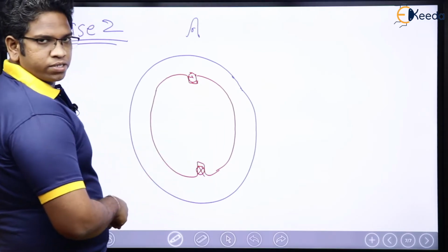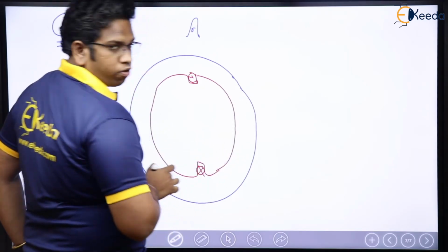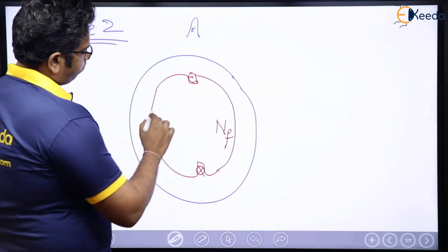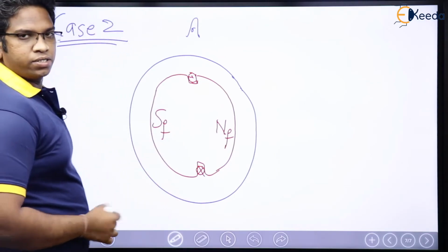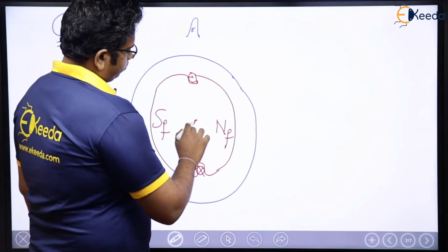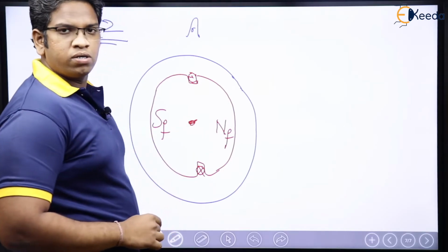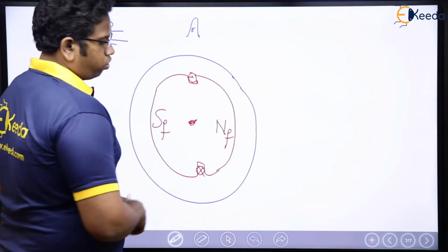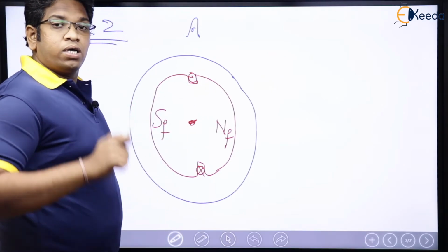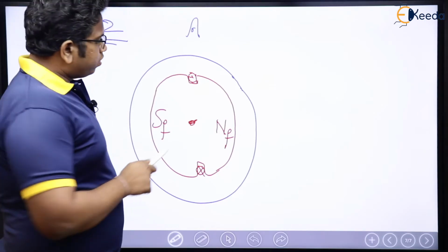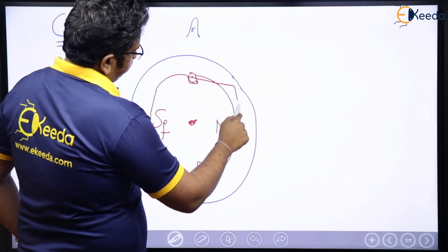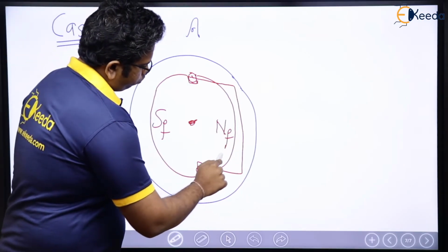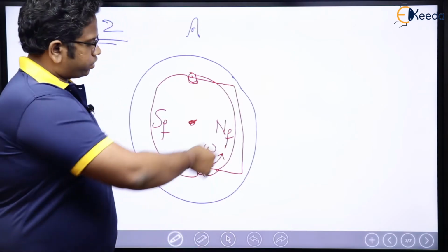So this is the way flux is going to be there. So flux is going to be out of the rotor from here, which means this is going to become north pole of the field, NF and SF. Why? Because we are considering it as non-sinusoidal, right? What? Non-sinusoidal means what? This one, flux distribution. Since this is cross and this dot, which means it is for what? One slot per pole. One slot per pole means this is going to become the flux distribution. And let me consider that I am rotating the rotor by omega speed in this direction.